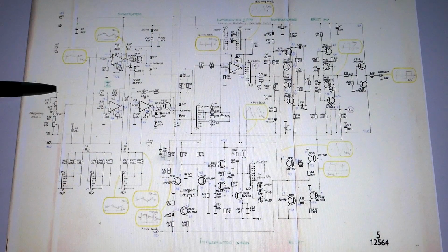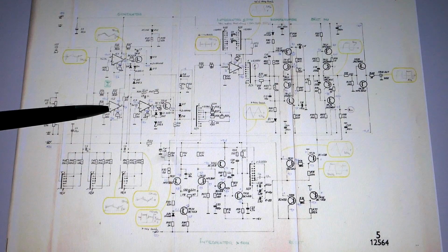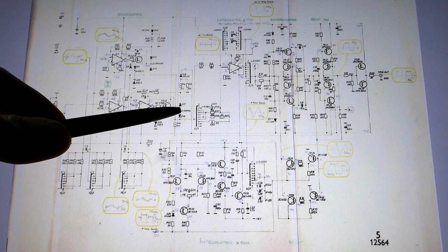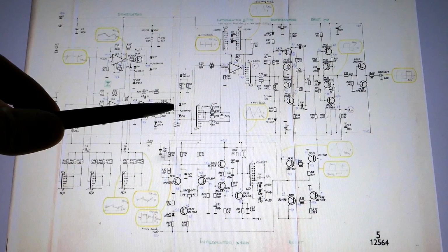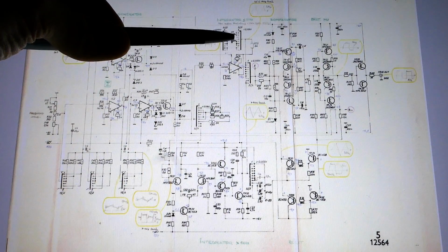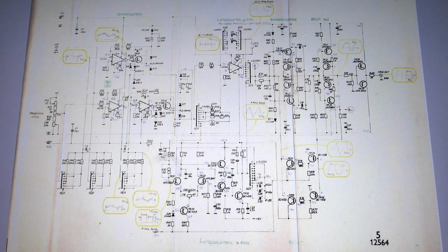It produces a negative voltage, and a positive voltage of the same magnitude is produced using the third op-amp. So this is just the polarity inverter for the control voltage, and these two control the transistors, and this basically reduces the voltage coming from the feedback to a specified level. And of course, the lower the voltage, the slower the capacitor in the integrator charges, and so the lower the frequency. At least I think it works this way because it's bloody complex. This is something you have to keep staring at for a long time to get it.